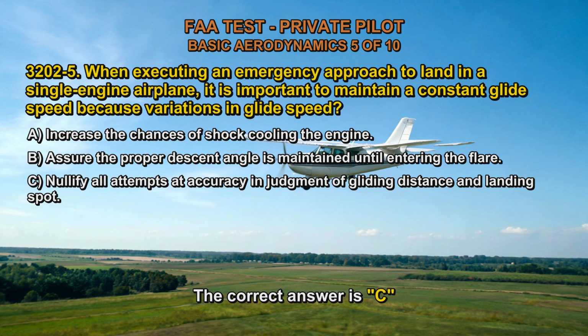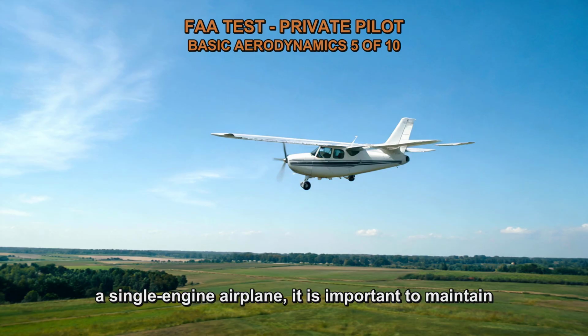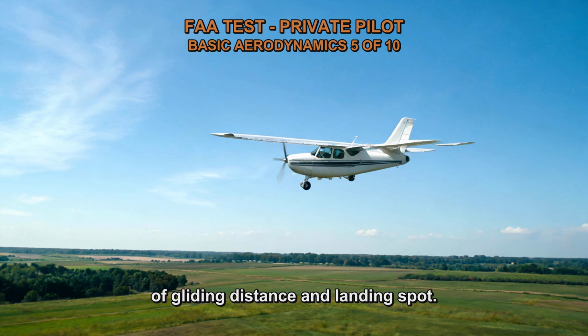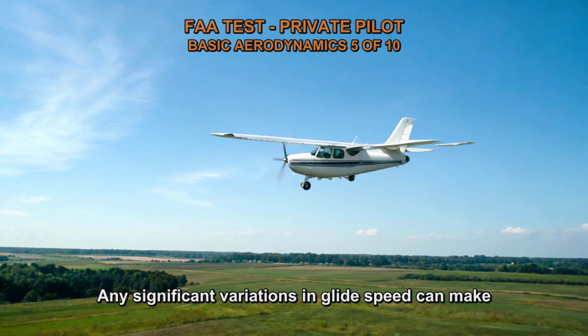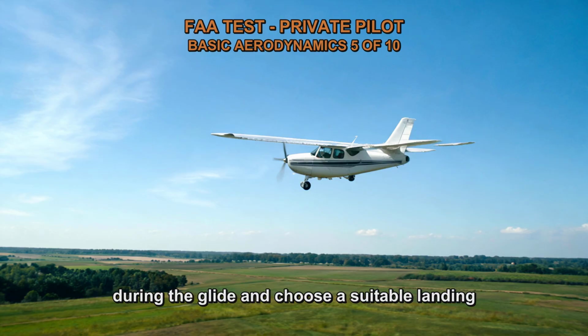The correct answer is C. When executing an emergency approach to land in a single-engine airplane, it is important to maintain a constant glide speed because variations in glide speed nullify all attempts at accuracy in judgment of gliding distance and landing spot. By maintaining a constant glide speed, the pilot can accurately judge the gliding distance and select an appropriate landing spot. Any significant variations in glide speed can make it challenging to accurately assess the distance covered during the glide and choose a suitable landing area.